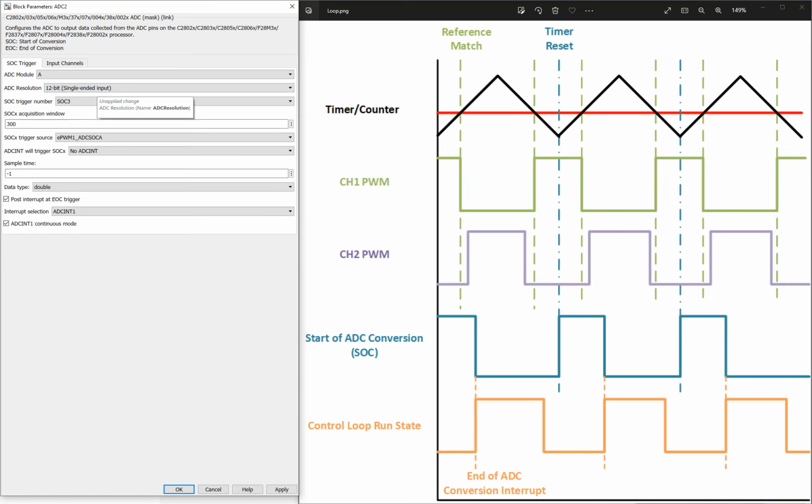The resolution for this ADC will be 2 power 12, that is 4096. So the conversion will be the range divided by 4096.